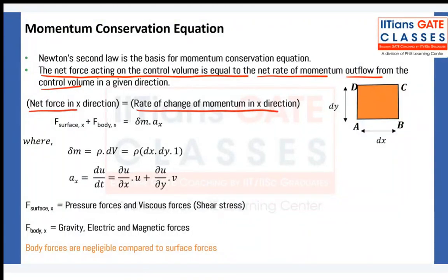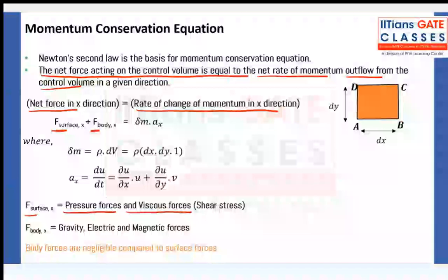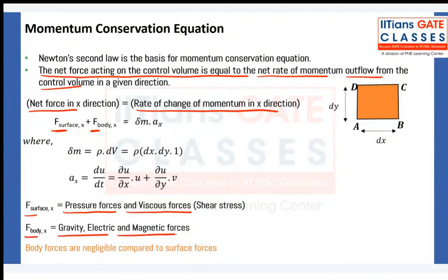What are the forces that are working? Surface forces and body forces. Now surface forces are pressure forces and viscous forces, and of course we are going to cancel our pressure forces later on, so we are not going to consider our pressure forces. Body forces are gravity, electric, and magnetic forces. Now in our analysis, body forces are negligible compared to surface forces, so this is what we are going to cancel. We are not going to consider this.